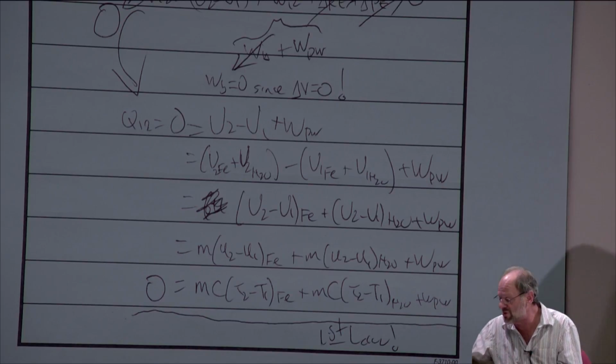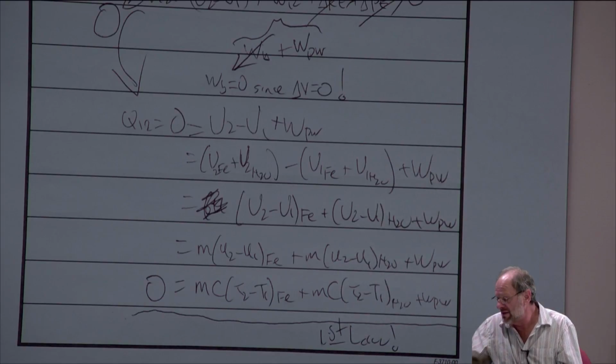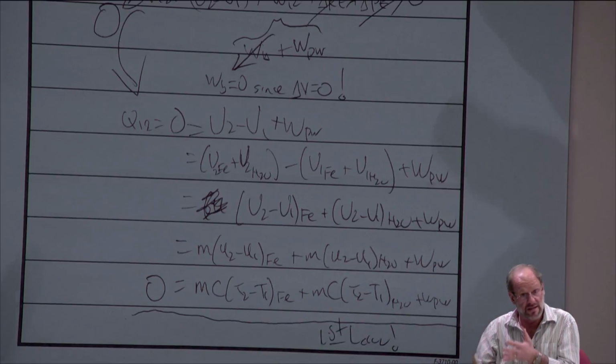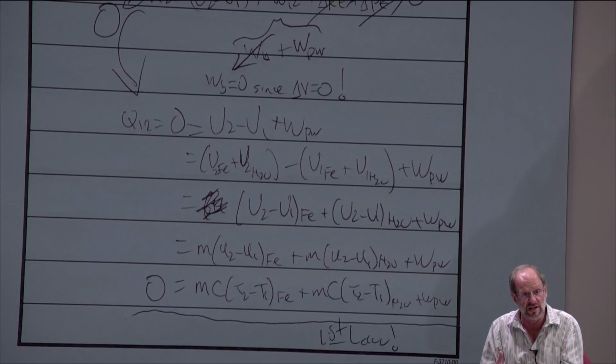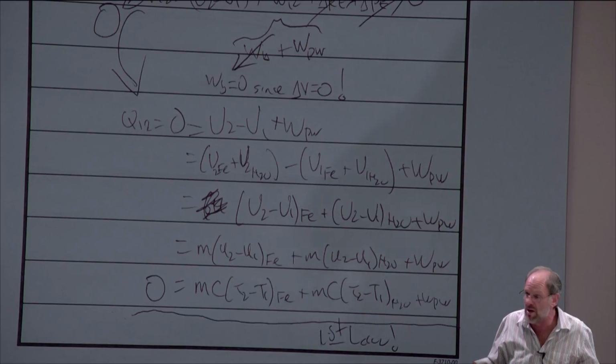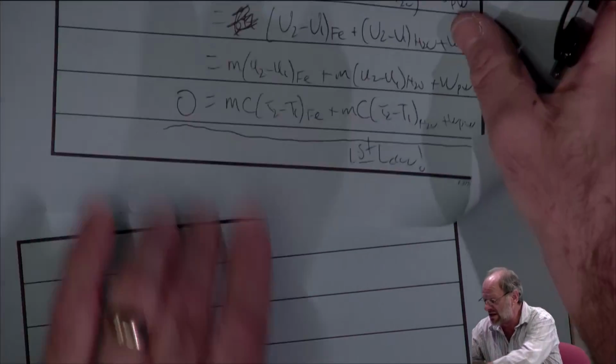So as long as we know the temperature of that water, we should be able to find the saturated liquid conditions. And if we know the total volume, can't we just use the specific volume of the saturated liquid and divide the specific volume into the total volume, and that's going to give me the mass of the water? So we really do have the mass of the water. We just have to calculate it.